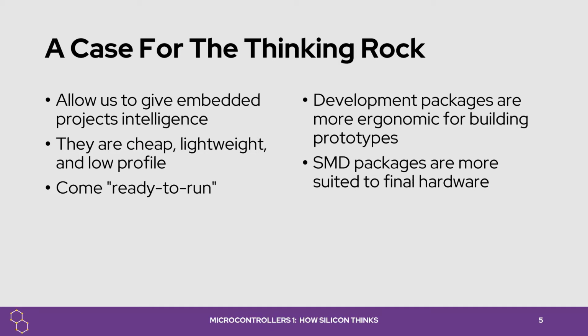Furthermore, when you've got a development setting, you're generally using the dev board, which is the version that comes with batteries included. That's simply because it's more ergonomic to develop on. It's got the USB interface, it's faster to flash. It comes with a clock generally, so you don't have to add any additional components. You can just drop it in and break out from the dev board, and you've got it working.